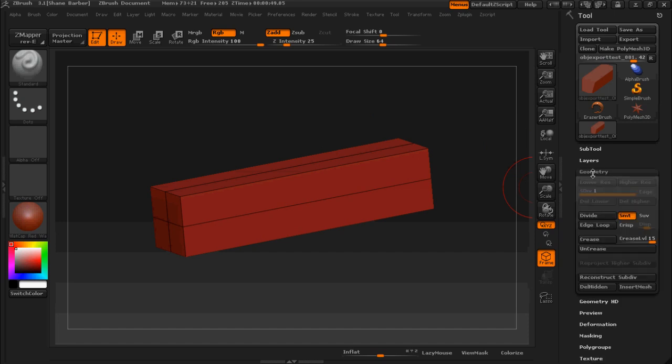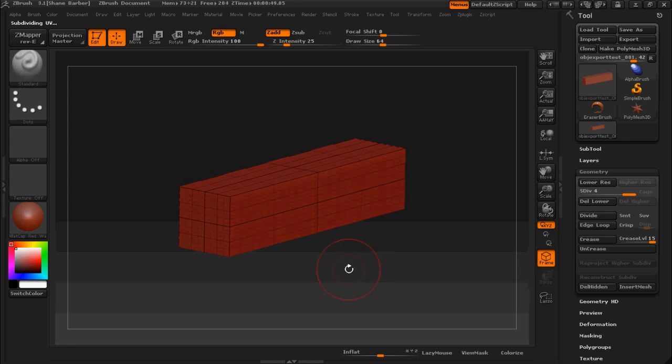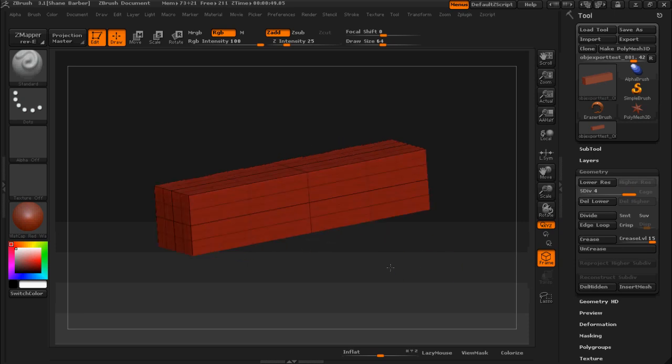So we're just going to go to Geometry, turning off Smooth Modifier. We're going to hit Divide a few times, and that'll let us bump up our resolution. And as you can see, we have some resolution. And already you can kind of tell the issue that we're going to run into in here. When you subdivide in ZBrush, it divides both horizontally and vertically, which means that a square ends up getting divided once through vertically and horizontally at the middle, and you end up getting 4 squares out of 1 square. So what we have here is some nice resolution that's been given to us. But if you notice over here that the polygons, since we didn't have an additional line here to start with, are all totally elongated and are going to be really poor for our topology in the end.